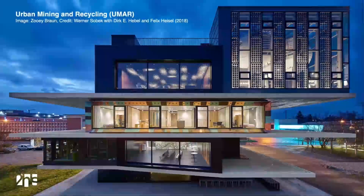Next slide. The other project I wanted to show you quickly is the Urban Mining and Recycling Unit, a project that we built with Werner Sobek in Switzerland. The unit that we're talking about is the copper frame in the center of the image, which is completely designed for disassembly. So every connection detail has been rethought so that all the materials that we put into this building can then be transplanted into another use, into another project at the end of this life cycle.